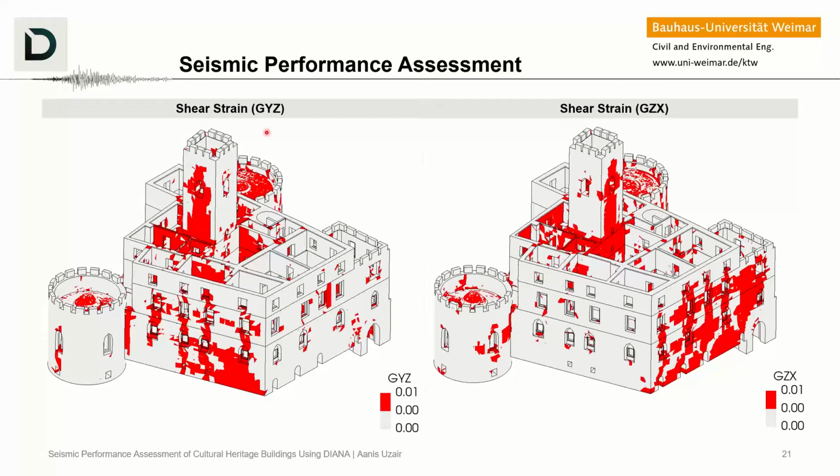When you are interested in a more detailed analysis, then we build localized models out of a bigger model, because then it is easy to refine the mesh, and it is easy to define the connections as interface elements, and derive more detailed analysis of a particular part of the structural system.